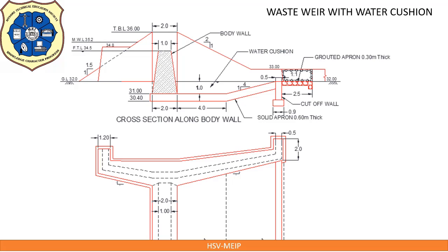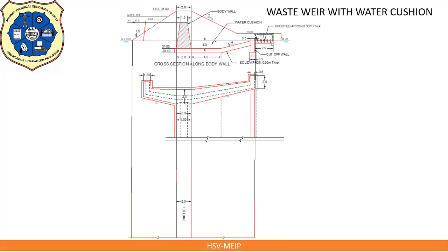Draw cut lines to draw half plan top. These are the cut lines so that we can show the half plan bottom. Project edges of earthen bund, wing wall and top width of the bund. Top width. And draw dark lines indicating top width of bund.